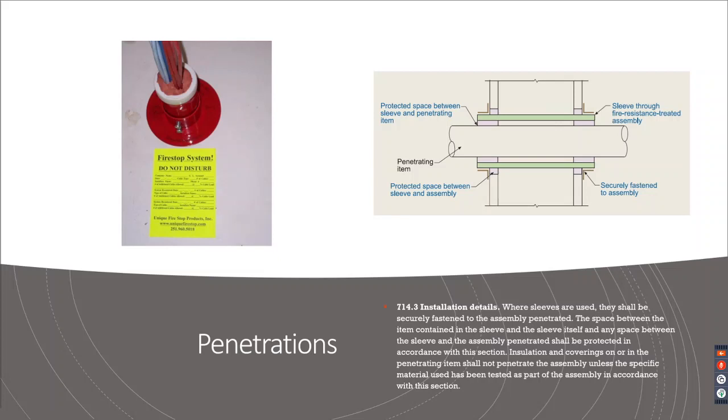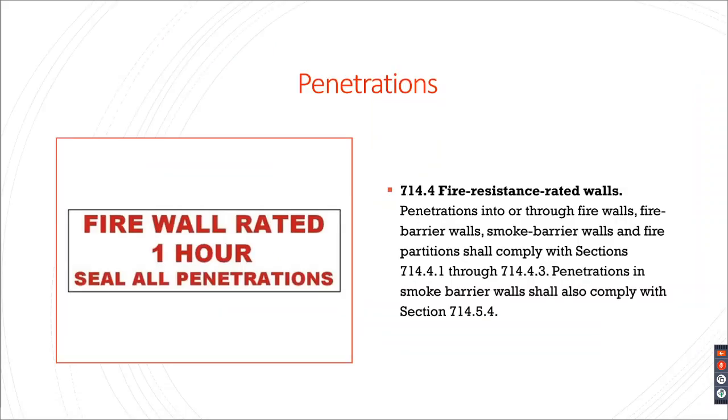I should have added that slide in here. I've got a slide that shows a small room. It shows the calcs for how long it takes a small room to fill with smoke with a dime-size hole in the wall. I don't remember the dimensions of the room, I think it's like 16 by 16 or something. It's really small, and it takes like 2-3 minutes, but it fills up pretty quick. But anyway, that's why this is all important. So this is talking about filling the inside of that sleeve, as well as where the sleeve is penetrating the assembly, the wall or the floor.